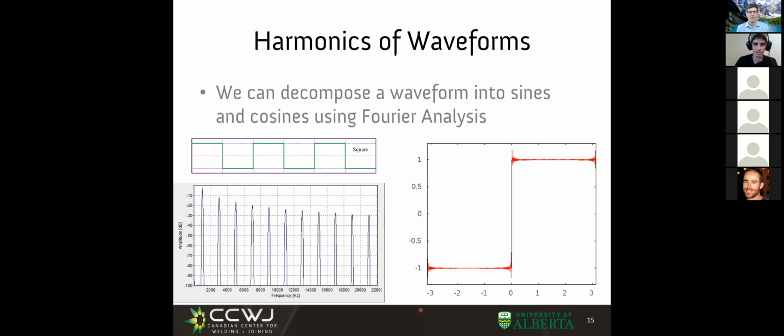For example, if you want to have a pulsed waveform and you want to be away from your power source, what some companies do is to do the pulsing in a small unit that doesn't generate power, but just controls the power and is closer to the weld. So you have a big power supply, long leads that are pretty much running on DC, and then you have the pulsing unit close to the welding torch, and it's much smaller and more maneuverable. Right.